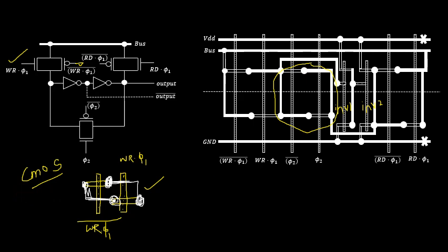So how are you following the inverter circuit diagram? Pull up will be a PMOS transistor, pull down will be an NMOS transistor, join the gate to gate connection, and you are applying the input to this. So this will be applied to the terminal of VDD, and this will be connected to the ground terminal. So this is VDD, and this one is the ground. Okay. Then in between the junction of PMOS and NMOS, we are taking the output. So this is one inverter.